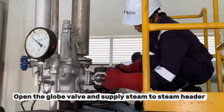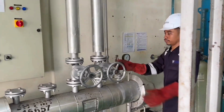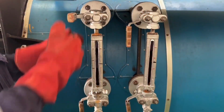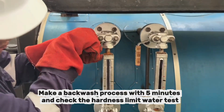Open the globe valve and supply steam to the steam header. Open the steam header and supply steam to the plant. Make a backwash process of 5 minutes and check the hardness limit with a water test.